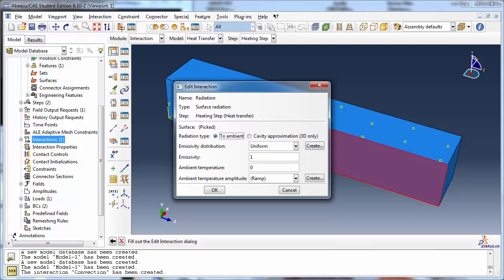The ambient temperature should be specified in degrees Celsius to stay consistent with SI units. Set it to 320 degrees Celsius. Basic heat transfer courses or experience in this area will tell you that the emissivity has no units and must lie between 0 and 1. Assume that our copper block has a thick oxide layer, which is known to have an emissivity of 0.78.